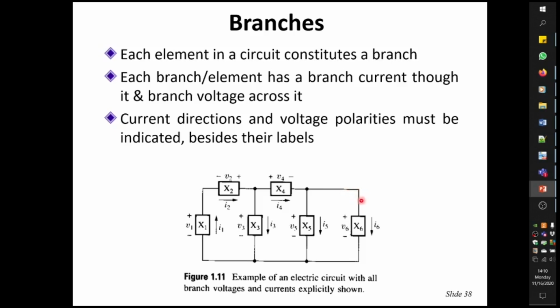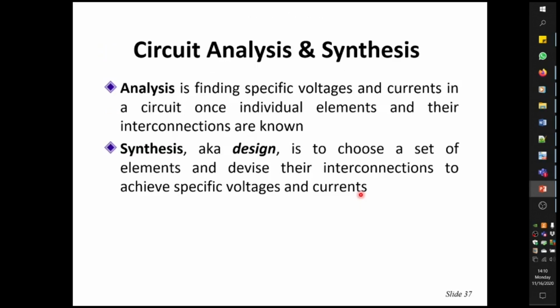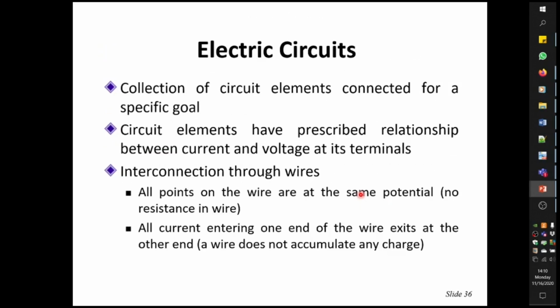They are either rounded off or we place an angle over here. The reason is that otherwise some capacitance will exist at this corner and it tends to store charge. These are things that you can study in high frequency circuits and PCB design, but that is not the topic right now.